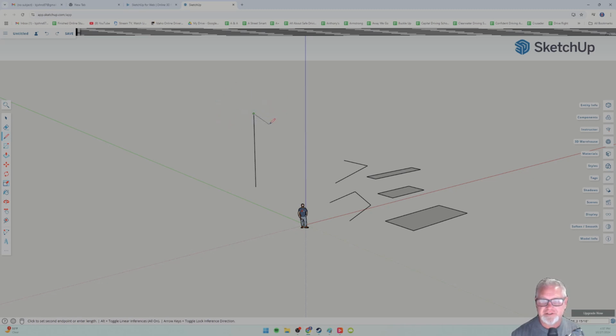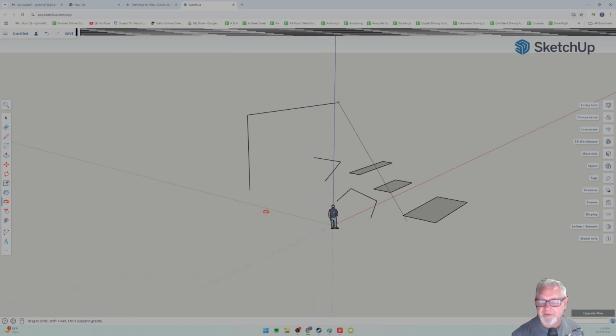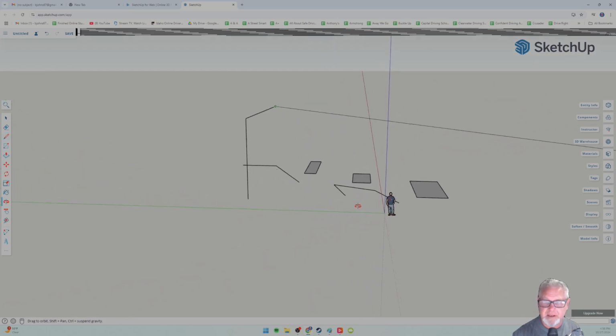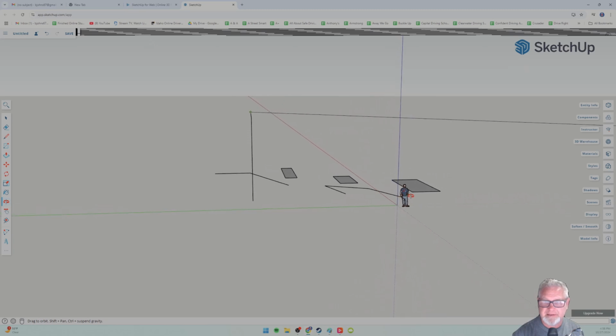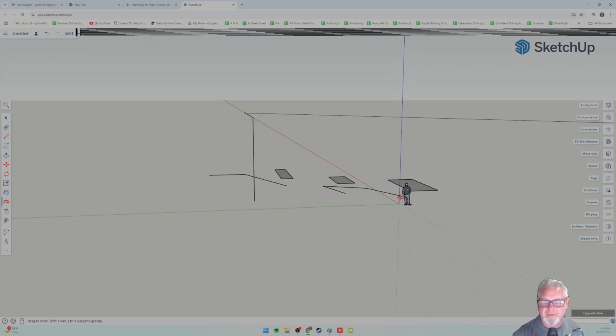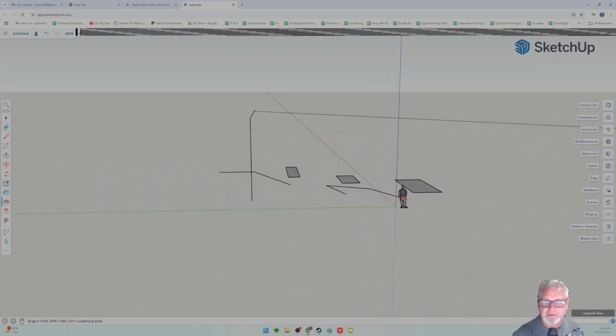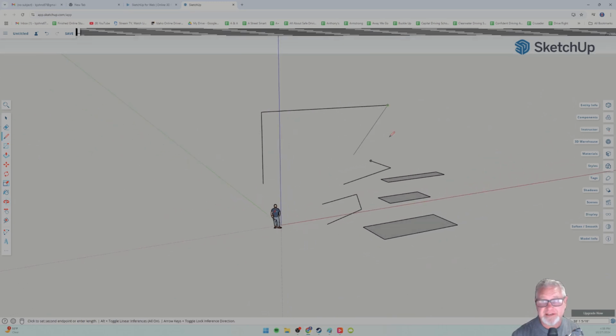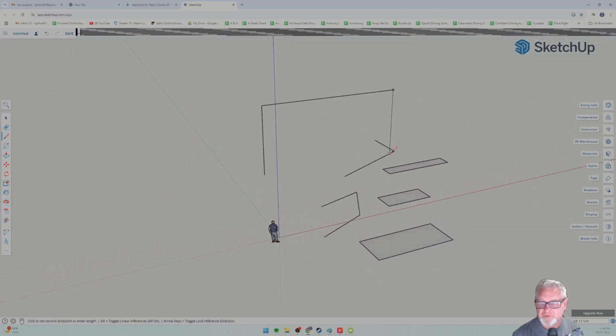If I wanted to go straight over, green is a good option. So that comes this direction, but make sure it stays green. I could also go red if I snap that direction. So I'm going to click, and if I drag my mouse, you'll see that it doesn't look like it, but it is on the red axis. Weird, right? 3D design is really deceiving, so you have to trust these colors.